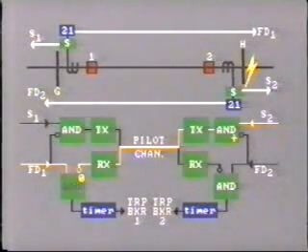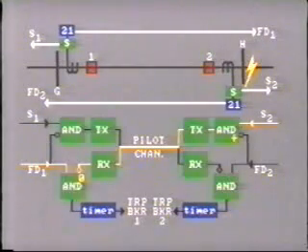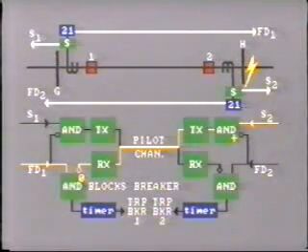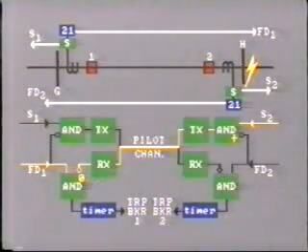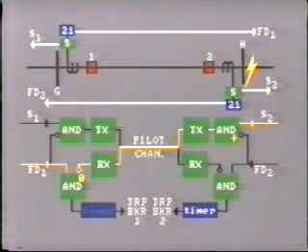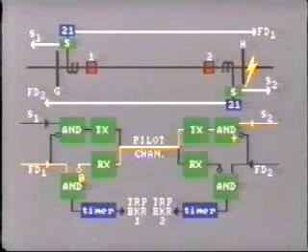As this logic box shows AND, it needs 2 positive input signals, one from the fault detector and one from the receiver. But at this moment, it has only one, that from the fault detector. So the breaker is blocked from tripping by the transmitted signal. To give time for signal transmission and logic circuit operation, the tripping circuit is fitted with a timer. So for this external fault, no tripping would take place.